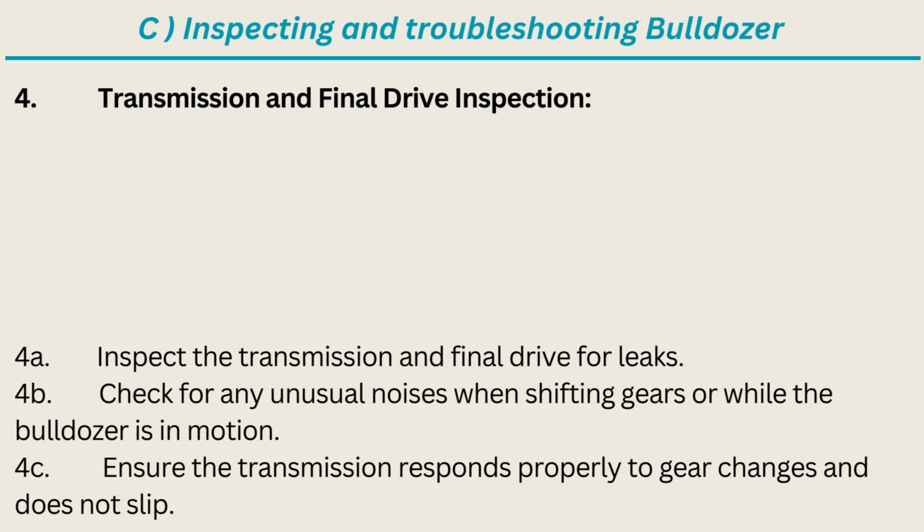4. Transmission and final drive inspection. 4A. Inspect the transmission and final drive for leaks. 4B. Check for any unusual noises when shifting gears or while the bulldozer is in motion. 4C. Ensure the transmission responds properly to gear changes and does not slip.